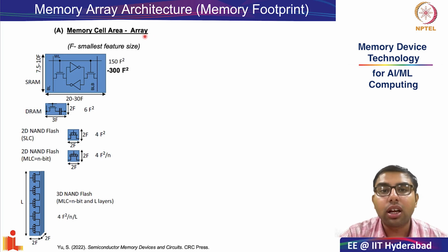When we were studying the memory hierarchy, we saw that as we go down the memory hierarchy and away from the CPU, the latencies suffer. However, the benefit that we get is in terms of bit density. This is because the area consumed by the device which is storing a single bit of information shrinks drastically. This is what we see in this schematic as well.